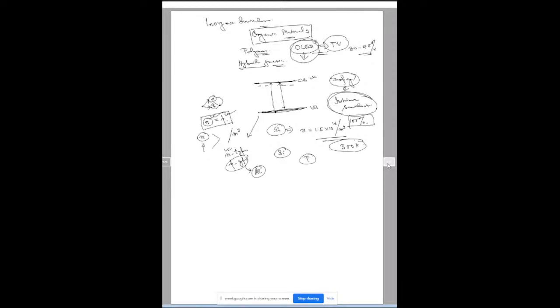Likewise, if you add a group 3 element, it will not be able to complete the covalent bond, because it has 3 electrons in the outermost orbit. One electron will fall short, so it will create a hole. That's how you can create a higher hole concentration as compared to electron concentration in this type of semiconductor. So they become p-type, holes are more than electrons, but nevertheless they remain electrically neutral. That should be remembered. So in an n-type material, n is larger than p.